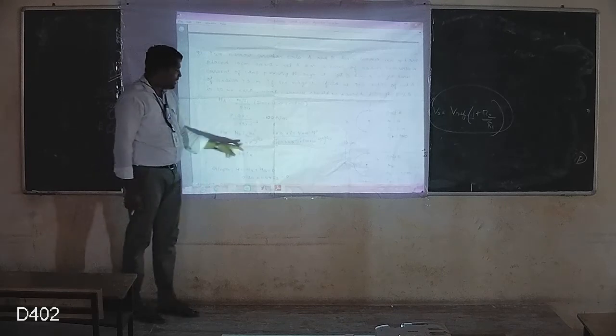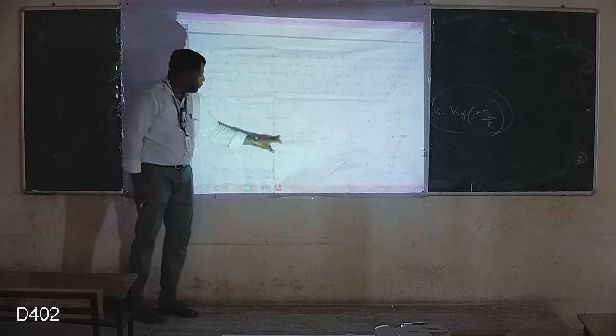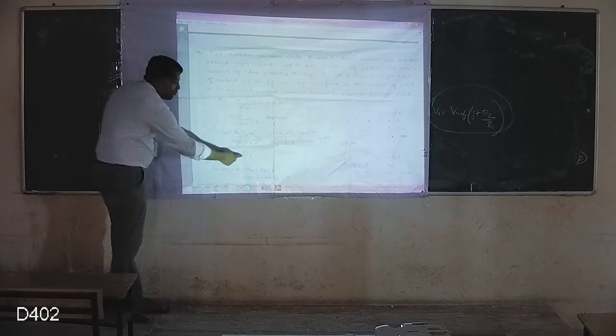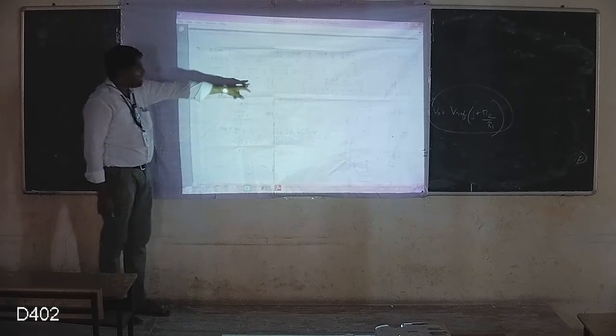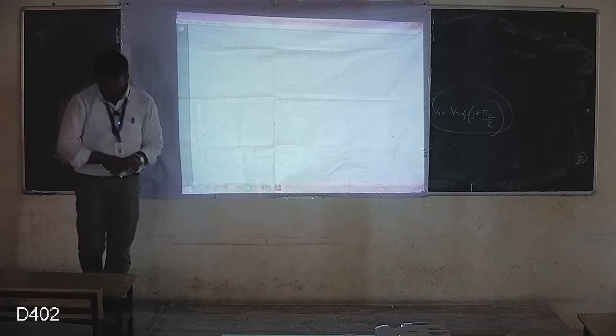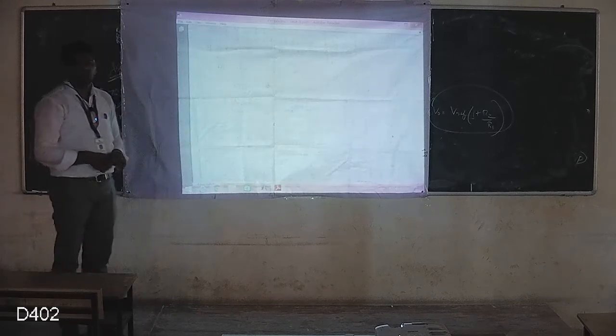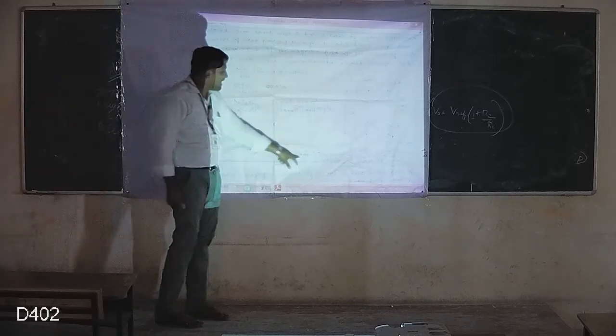With this substitution, I don't know what I2 is, so I am substituting I2 as it is. So I will get 1.44 I2. If I add those two, it is equal to 0. So 100 plus 1.44 I2 is equal to 0, and hence with the substitution, I will get I2 is equal to minus 69 ampere.